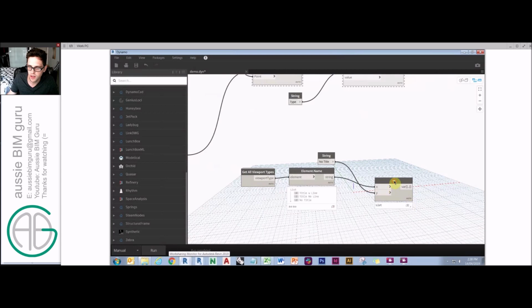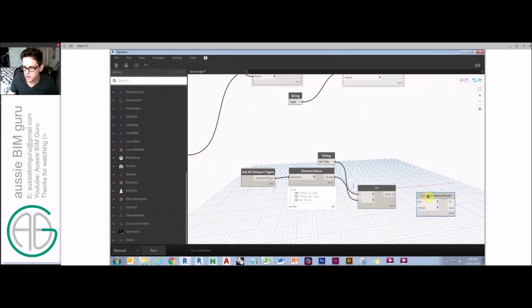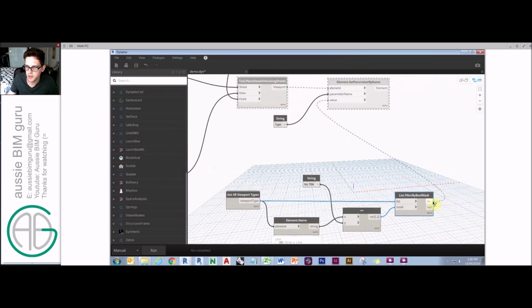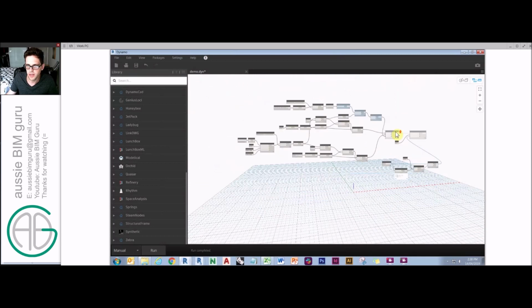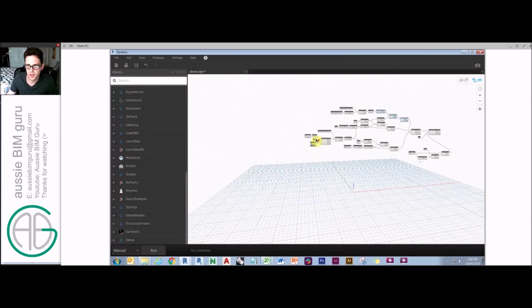And then you can see it's going to get us that index, and we just filter the list by bool mask. So we'll get that viewport by filtering on that true/false condition, and our only true is no title. So we're basically pulling through that, but instead we'll get through the viewport type itself. And there you go. So this is something we can feed in as a parameter now into here. So essentially what we have now is a full script. So this would work. So I'll just show you it in demonstrated format.